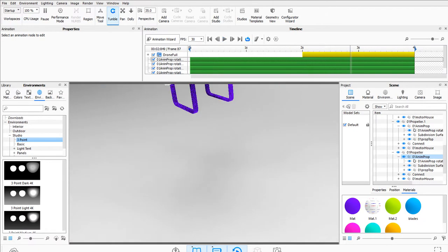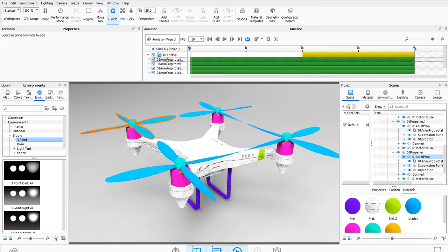If you remember when we modeled this, what did we do with every other propeller? We flipped them, right? Because in order for them to go correctly, they would be opposite, right? So I know that my first one up here, which is propeller 3, there he is, right there. That one is going the correct direction. So this one and that one should go the opposite direction.